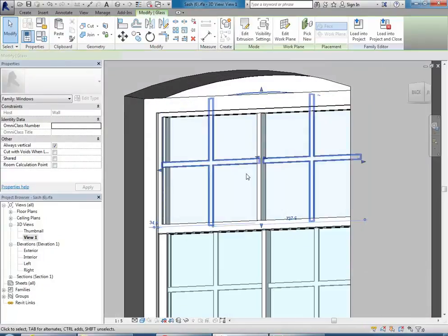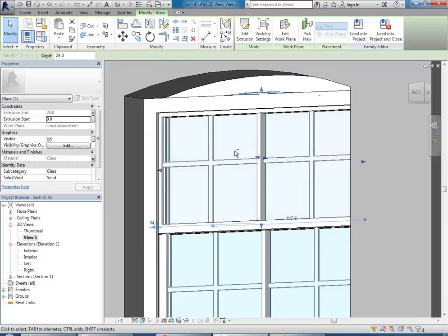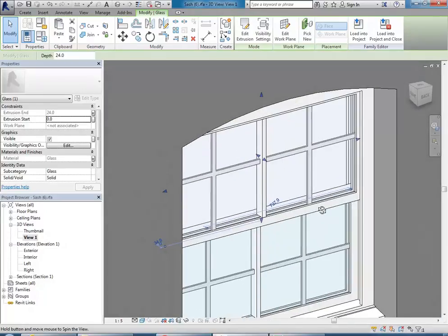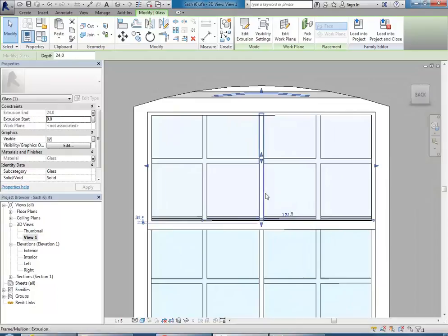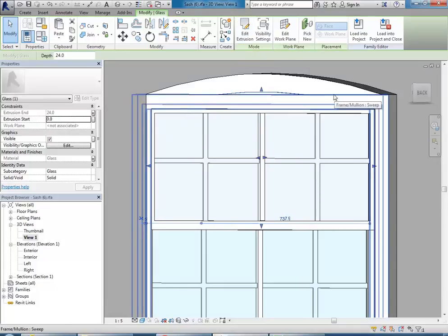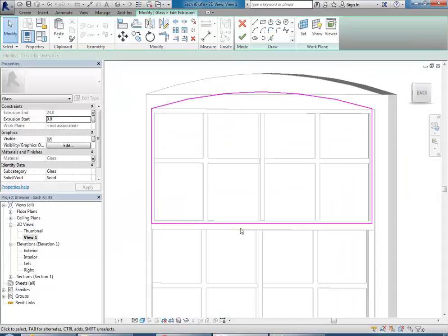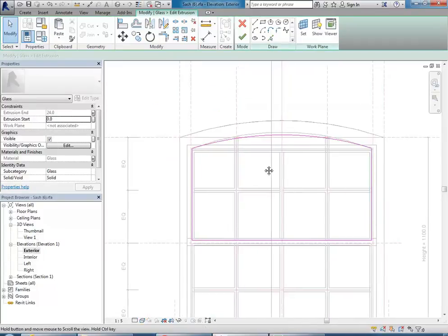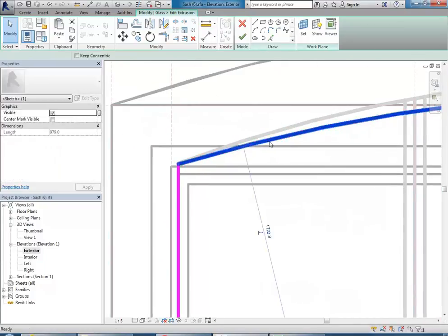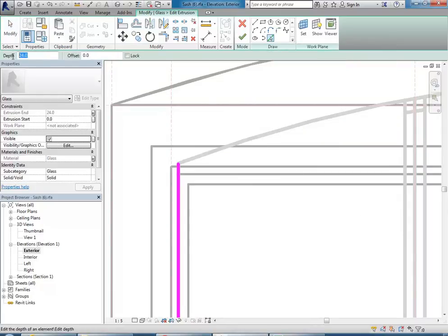So I've just got this inner bead, I suppose it is. It's just the inner part of the sash frame. And again, this one needs to be made straight, but it's made with an extrusion, so it's a little bit easier. Honestly, I don't know why they didn't do all of it with extrusion, but anyhow, this one should be the easiest of the lot. So going to the exterior view, and then you can delete that curve again, and this time just use pick lines, turn the lock option on, and pick this edge here, and then trim.